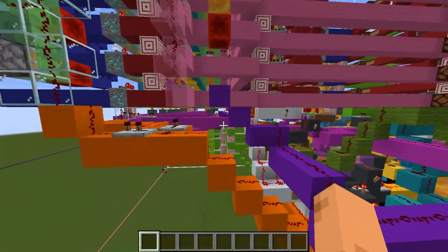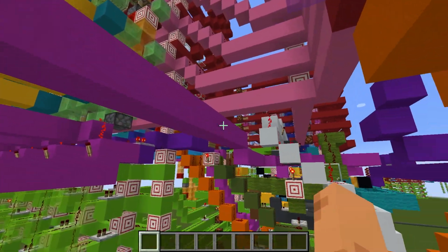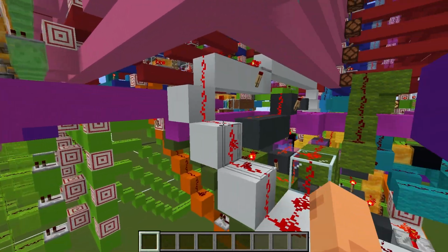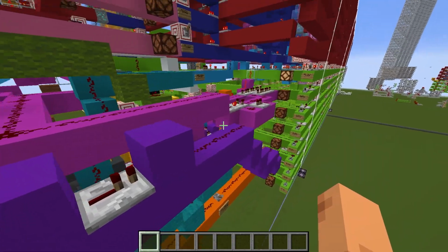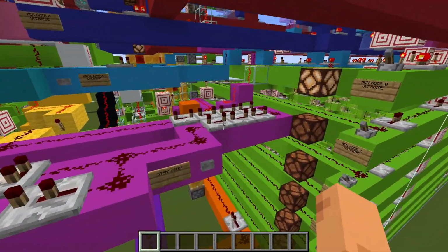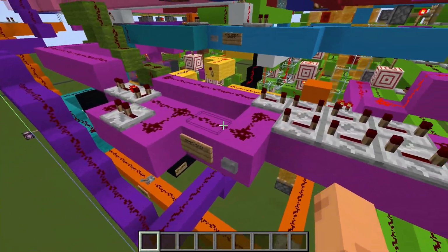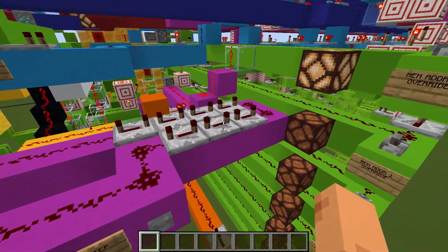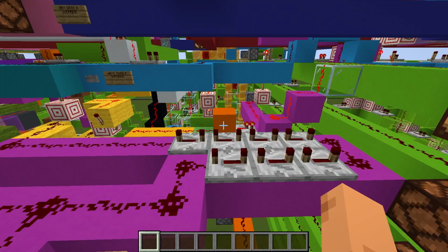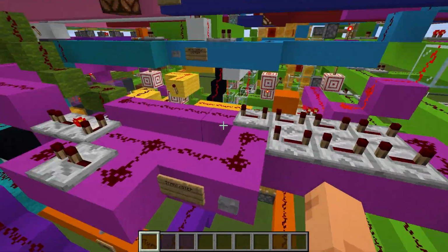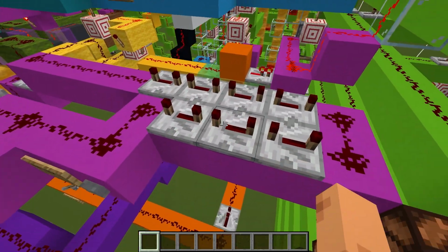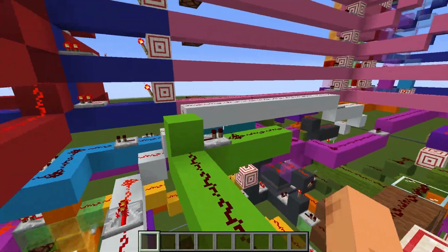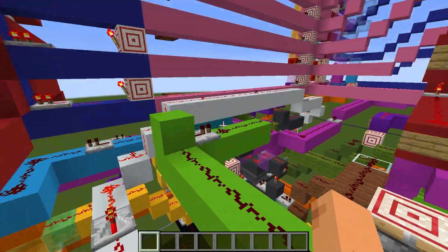And so that signal, again, is the purple or magenta wire line, gets down to here, and this is actually our clock line. So here we get down to the final clock line, and I believe this amount of delay here is for the memory controller to write, and so this is kind of a fixed delay. It's probably for the memory controller and the control unit to decide the next instruction. So there's our loop of our clock.